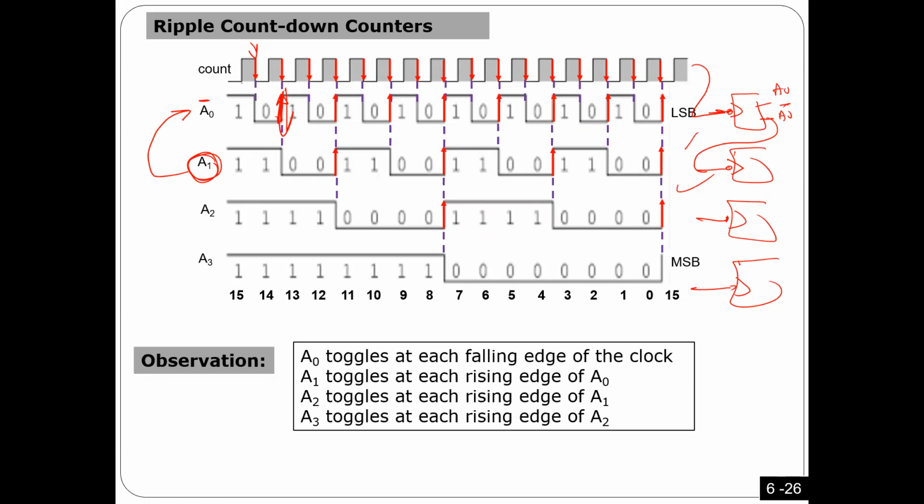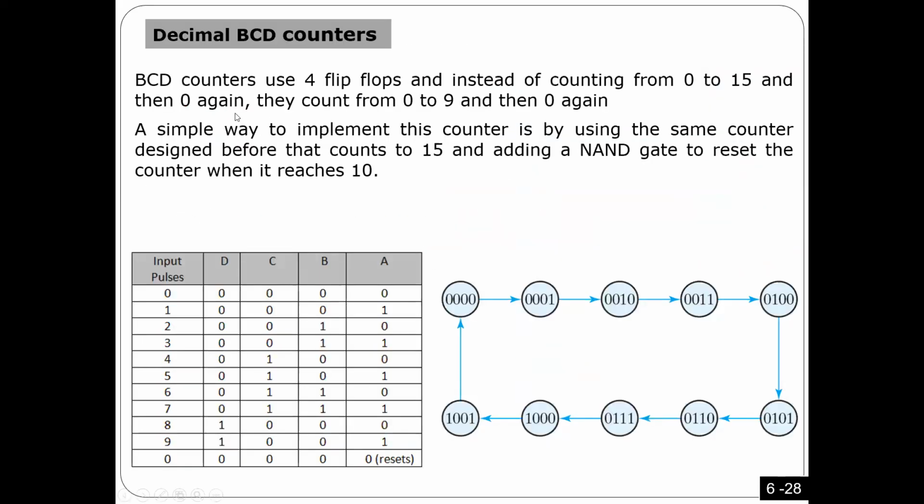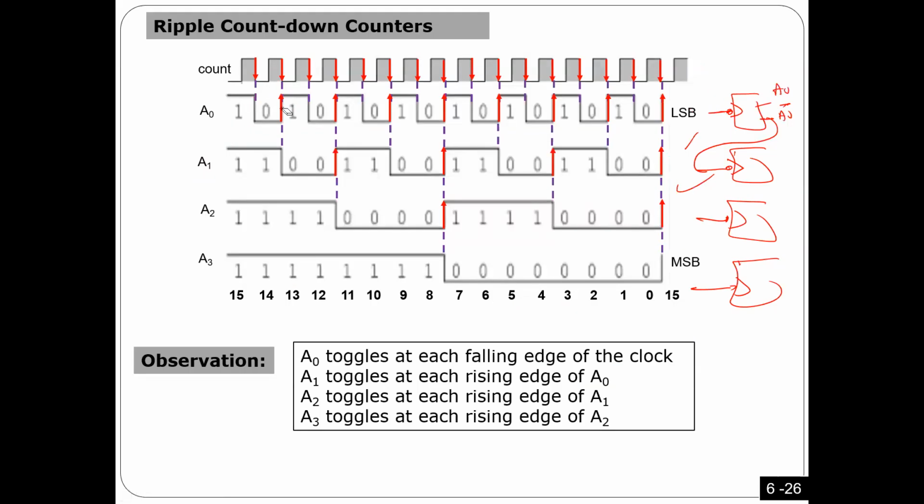So you have this signal, E0. I can't use this one, because this flip-flop triggers at falling. I want to trigger it at rising. So instead of taking E0, I'm going to take E0 prime. In E0 prime, this one will be 0, this one will be high, and then this one will be high. Look here, this rising is going to become falling. Maybe I want to draw it. Let me draw it here. You got what I'm saying? So every rising in E0 prime is going to be falling.